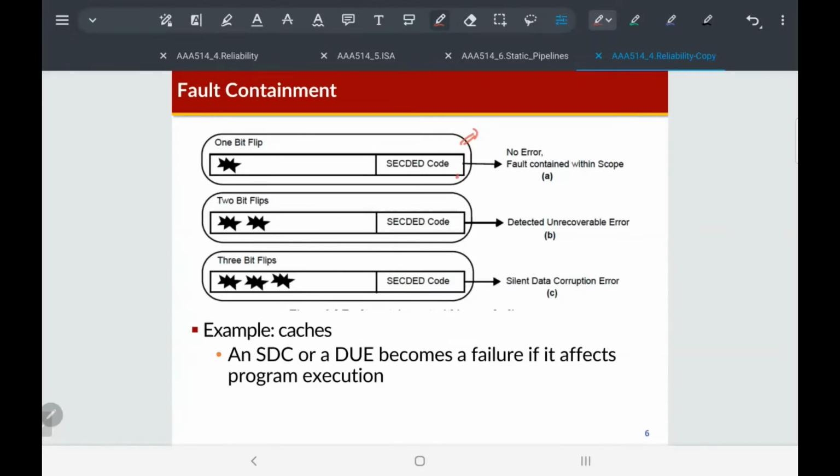So if one bit flip happens in an entire memory row read, we can recover this one bit error with SECDED. And if 2-bit flips occur in some data read from the ECC DRAM, then we can detect this error, but it is not corrected. Okay? It's just a detection.